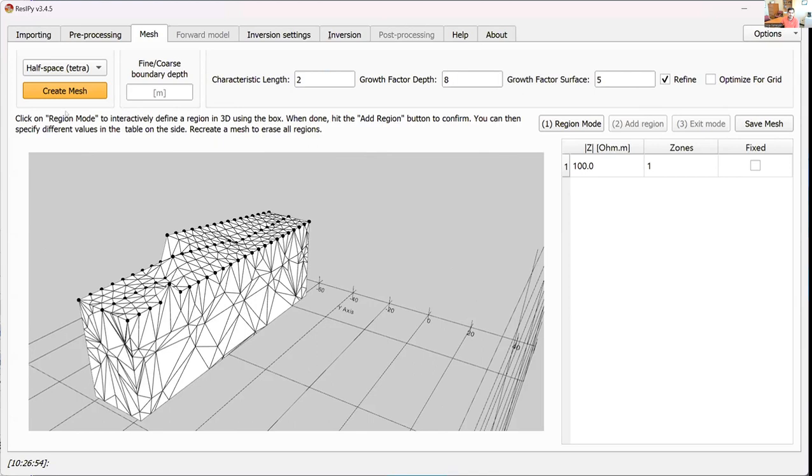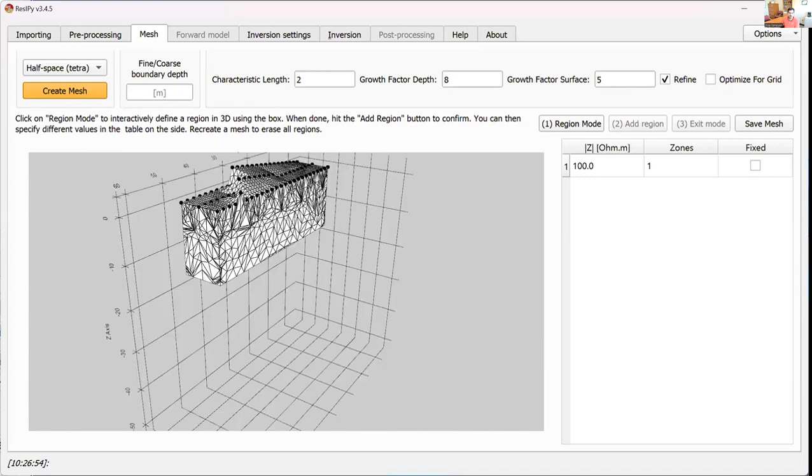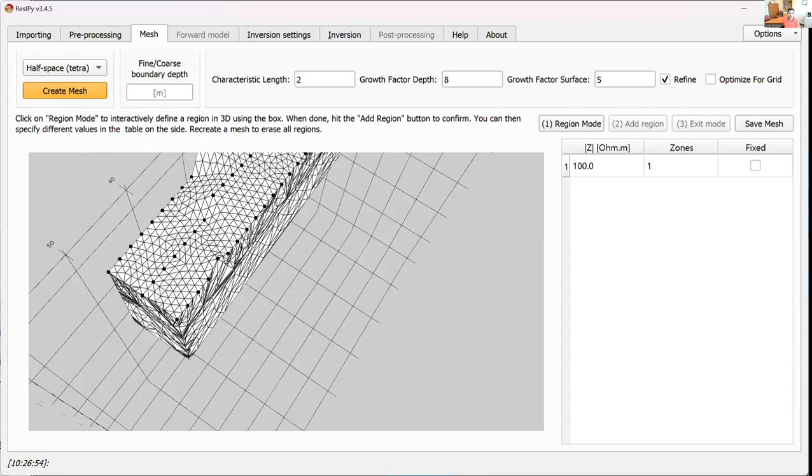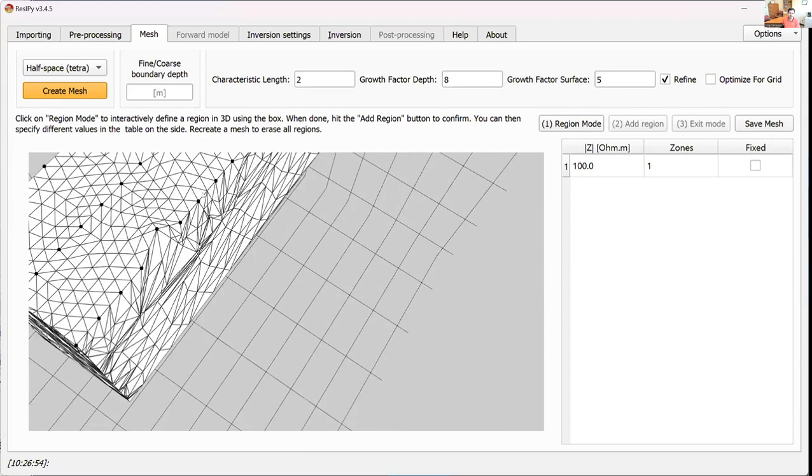So if I do that, the format will be the same, but the cells will just be smaller. You still have the same big mesh element size, but they're smaller. That's what the refining does for you. Now you can see between 2 electrodes, prior to this was just 1 element, now it's 2 elements, so divide everything by 2.